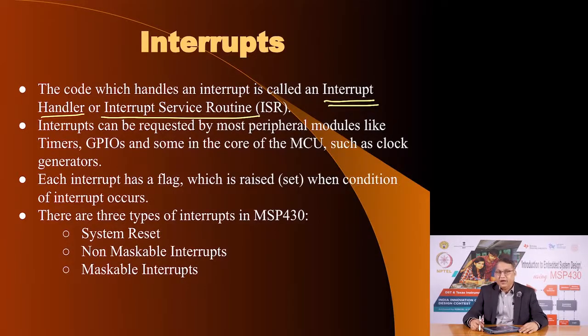Interrupts can be generated by most peripherals in the MSP 430. They can be generated by general purpose input output pins here, as we know that on the MSP 430 that we are using on our lunch box, there are two ports, P1 and P2. Any input pin on P1 and P2 can generate an interrupt. Each interrupt has a flag, and when that flag is raised, the condition for the interrupt is satisfied and the microcontroller will do something in response to that condition.